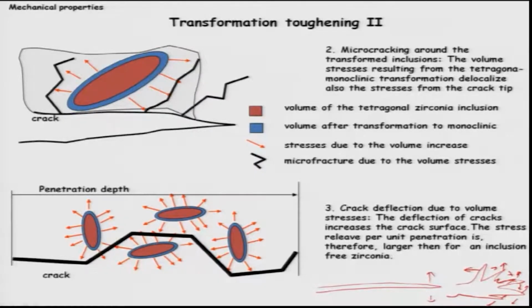So because of volume increase, what will happen? The region here will be tougher because compressive stress has developed, so the crack cannot pass through it. The crack will then propagate through regions where there is less compressive stress, or rather most tensile stress, because it can open and move fast. In this way it can follow a treacherous path, or it can actually deflect.